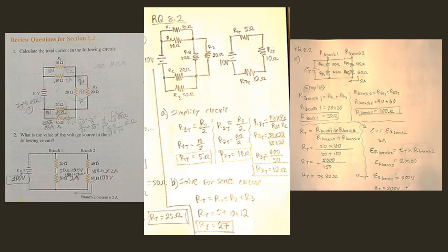Remember, those are both now in parallel, so we have a purely parallel circuit, and we can go ahead and find out our voltage drop, since we now have the voltage drop at branch 2, and we also have shown on the problem the branch amperage, or the branch current. That's all we need to find the branch voltage drop, which in this case, being a parallel circuit, we know that our voltage drop at branch 1 equals our source voltage, so we go for that.